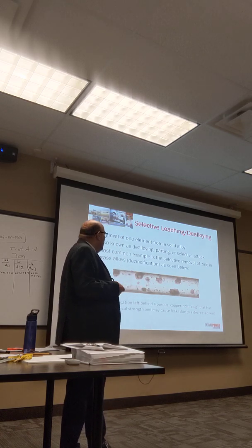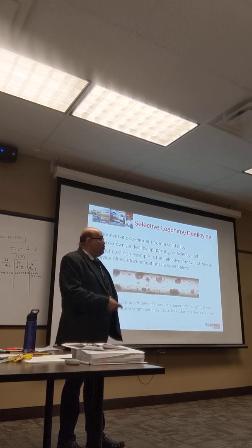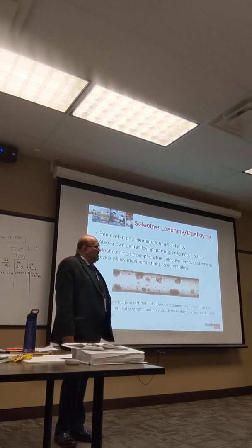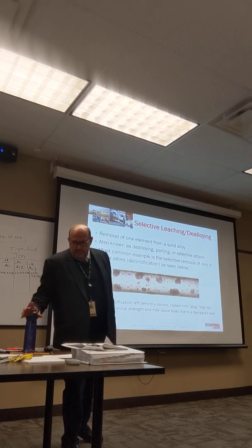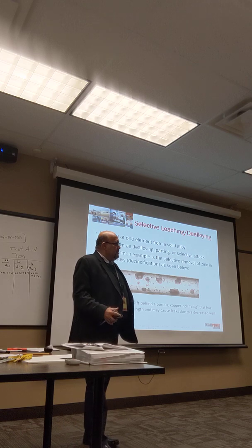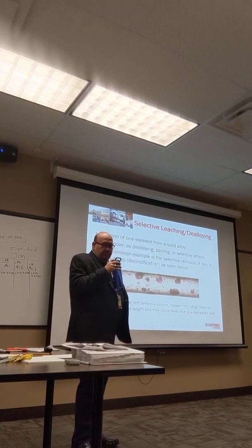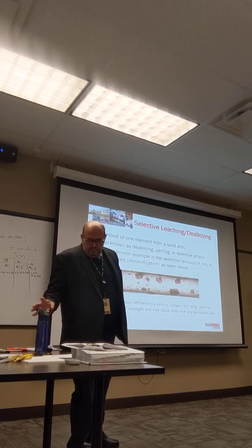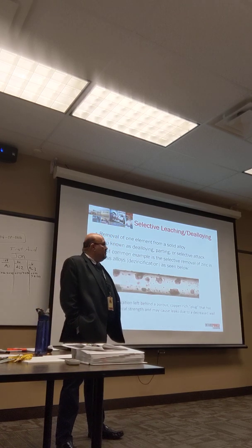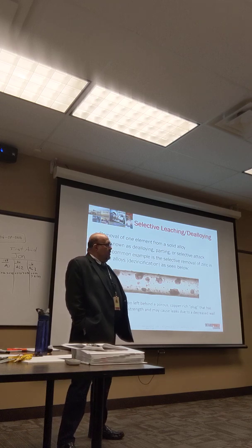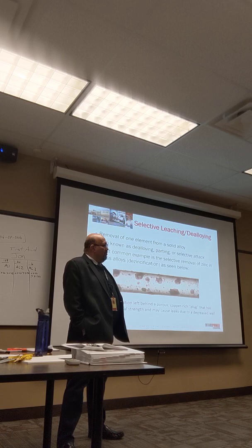And so this is also another case Andrew was talking about. Would you like to share with us? In our Pickering shutdown cooling pumps, the mechanical seals have a ring that's made of tungsten carbide with a cobalt binder. So we have to replace these seals every outage, which is excessive.